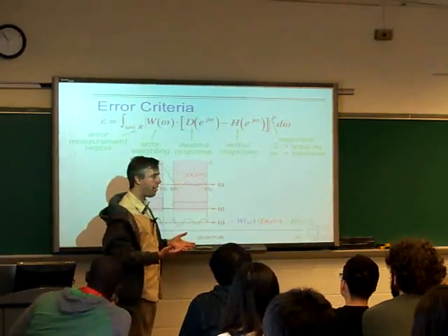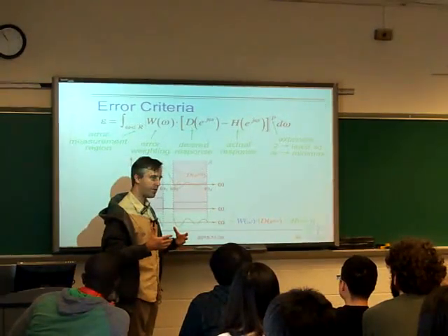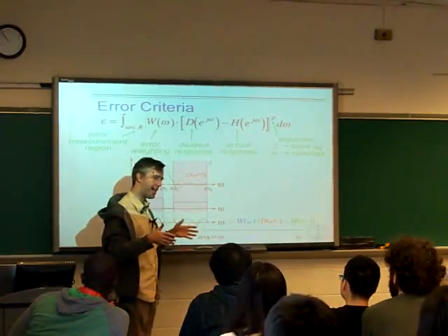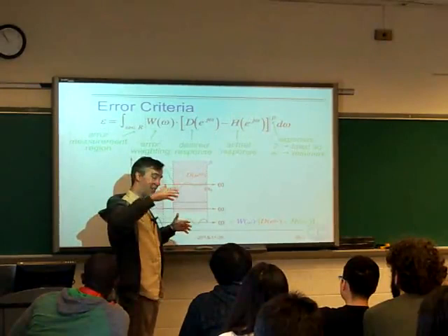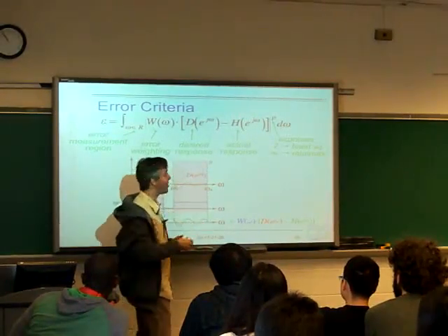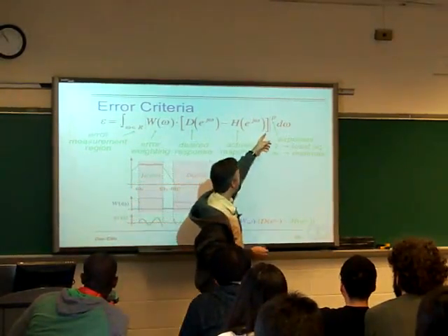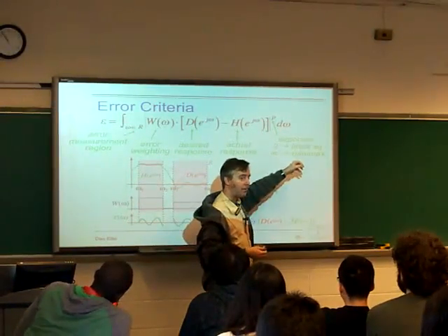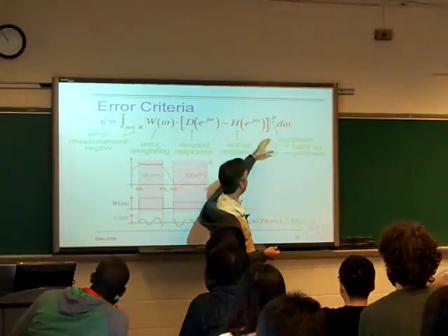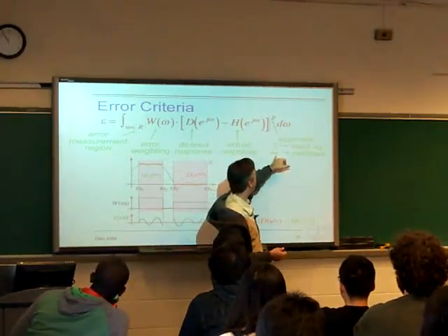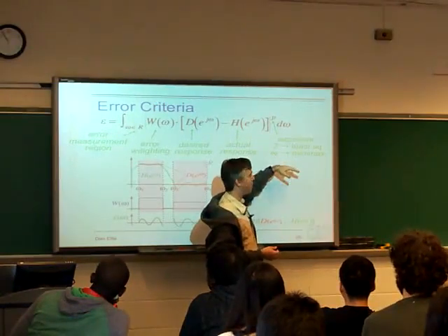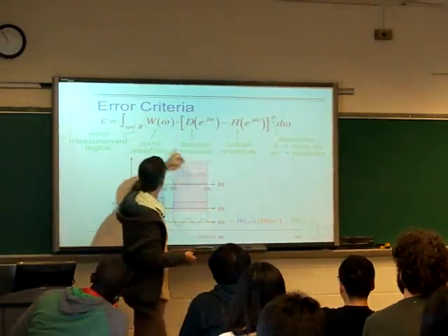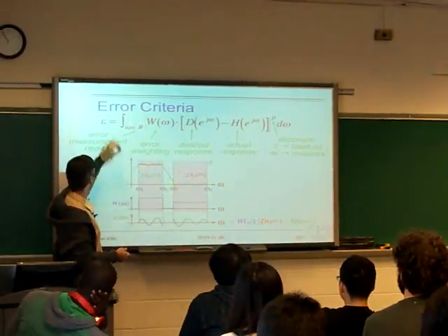The higher the power, the more large values become important, right? If we think of taking the sum of the absolute values versus the sum of the squared values, then squared values tend to put more weight on larger values. And in fact, if we let the exponent go even larger, then the largest value for any value of omega comes to dominate. And so in theory, p equal to infinity tries to optimize the single largest value. And then we integrate that over all frequencies, or over all frequencies within a range, to give us our error function.